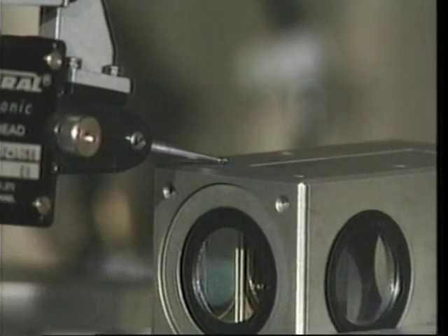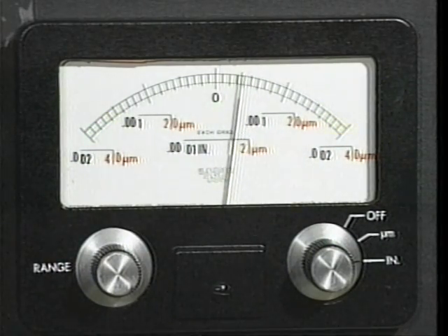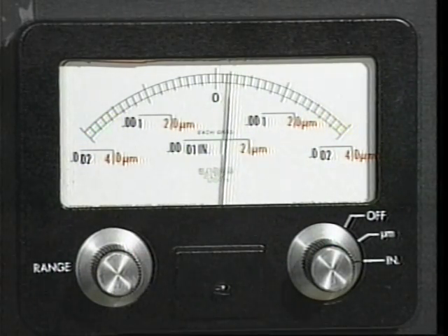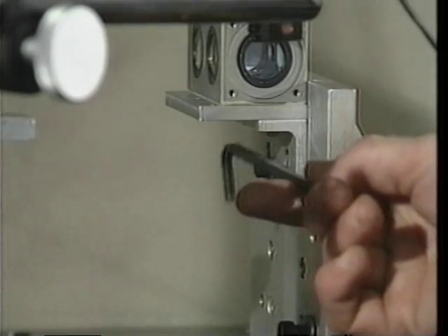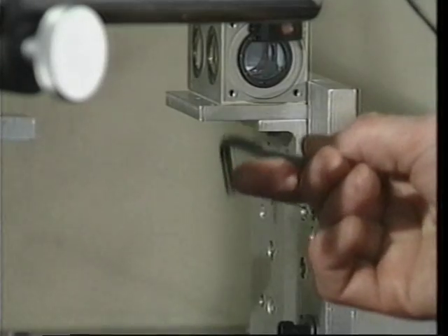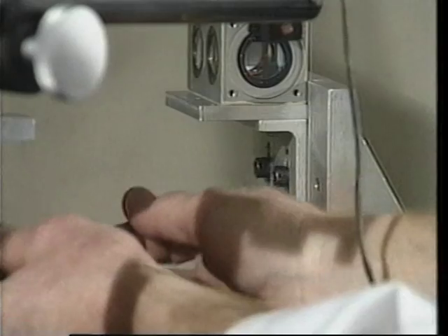Note the orientation of the stylus axis with the transverse direction. The variation in the gauge reading is monitored as the stylus is traversed. Based on the amount of tilt indicated by the display readings, the position of the interferometer is corrected by adjusting the support bracket.